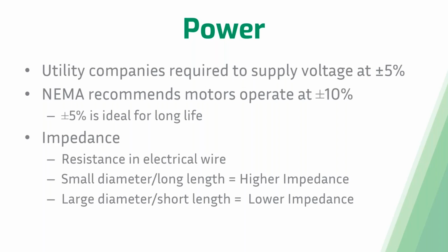And that's really to ensure that that pump is going to operate no matter what supply voltage is supplied by that utility. However, it's important to know that you want that motor and that supply voltage to be as close together as possible. And that's because the closer you are, the longer life you're going to get out of that pump.